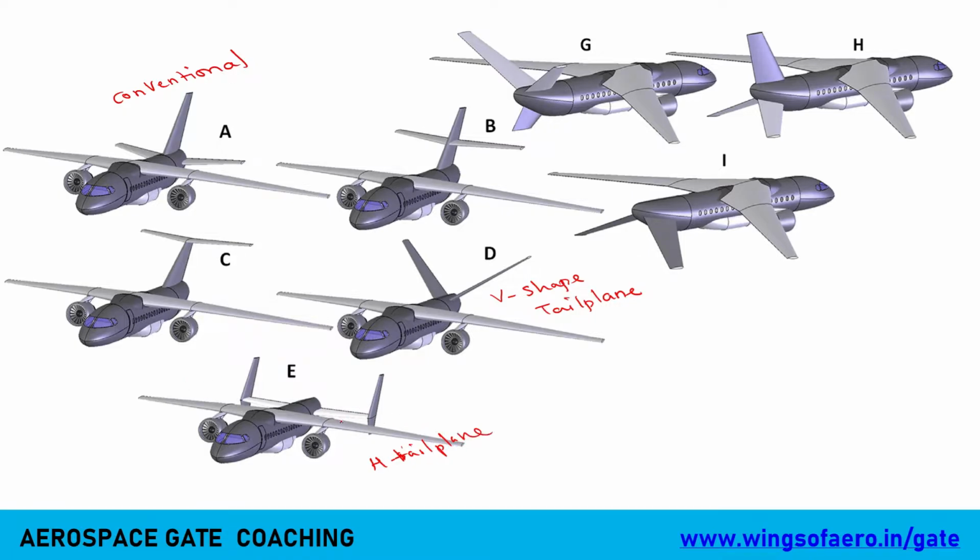Now this type of configuration, you can see for the smaller aircraft. Mostly this conventional pattern is widely used for large, like cargo aircraft. Even for cargo, it depends on a lot of factors. Now I would like to give a unique difference between A and C. C is a T-tail configuration. The T-tail plane configuration, as I've said, is mostly used in business jets.